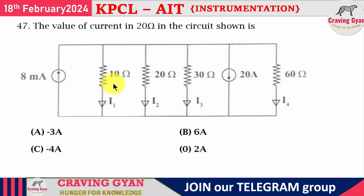In the 47th question, they are asking for the value of the current in the 20 ohm resistor. Here you will have two principal nodes. One principal node needs to be connected to the lowest potential. For the other principal node, I am going to take the nodal voltage as Vx. I am going to assume all the currents are leaving and then solve. When you write the first step of the nodal equation, you can eliminate two options.